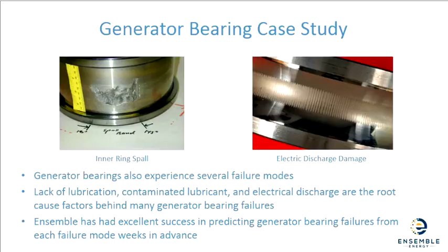In the case of a main bearing or a pitch bearing, these bearings move much more slowly. Therefore, the damage develops more slowly, and you can have a longer horizon. On the main bearings, we can predict that many months in advance. Pitch bearings also, we can predict those failures 6 months in advance. In the case of the generator bearings, it's more like a few weeks in advance in terms of the prediction horizon.